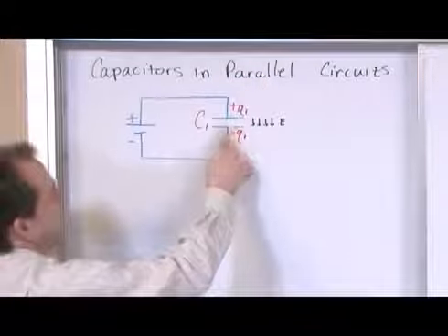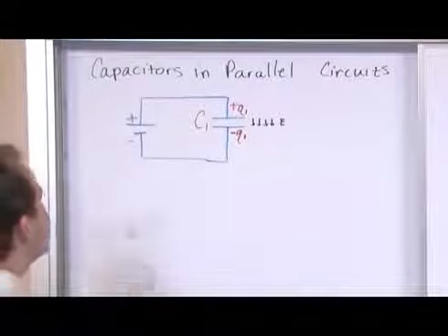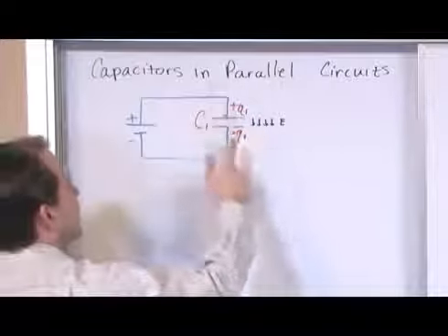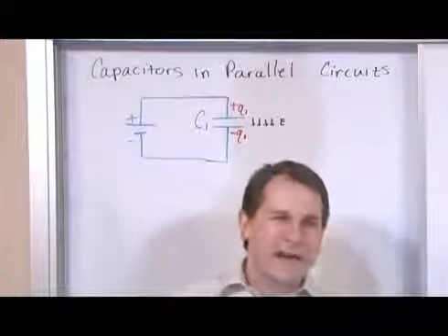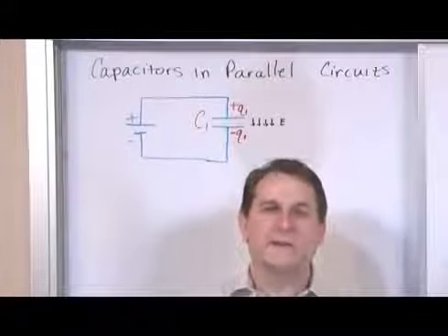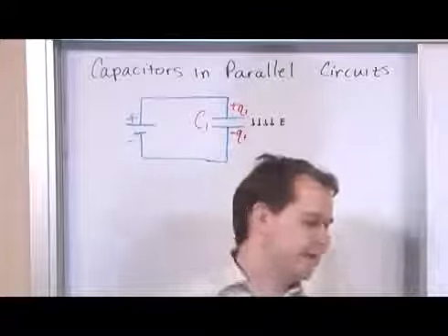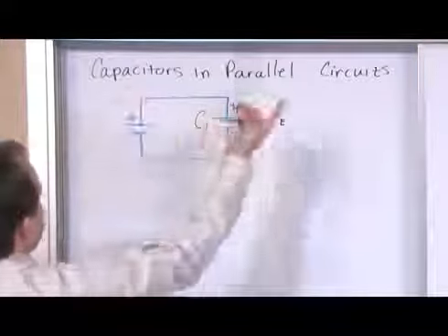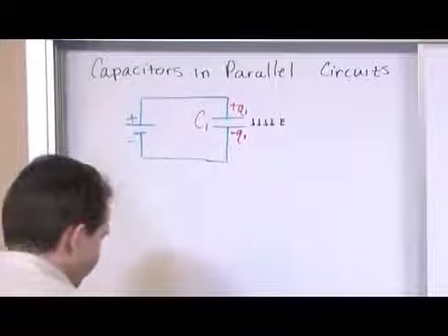So you can sort of think of these charges on this other plate as induced charges. The current piles up here, and then this sets up an electric field which then pulls electrons over to the other plate. So they're sort of induced. The reason I'm telling you that isn't because you have to think about that in your circuits. You don't have to think about that in your circuits. But in a second, when I do a proof and show you something, we're going to revisit that. So let's put this on hold here. I think it's fairly self-explanatory. You have positive charges piling up here and negative ones piling up there, and you have some energy storage in that capacitor, and everything's wonderful.